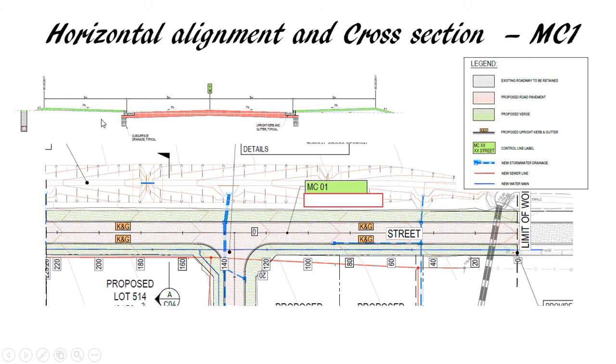towards the top of the curb. And because of the drainage, we have designed subsoil drainage in here, so that the water from capillary action can get filtered in here and gets into here, and somehow there will be a discharge point along the way or somewhere else, as you can see here.